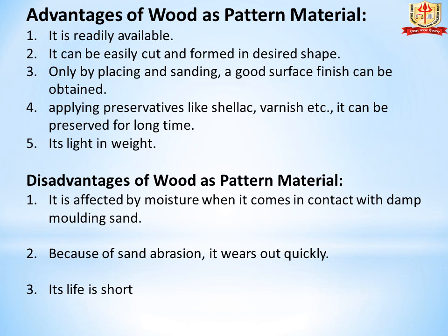Now see the advantages of wooden patterns. Advantages of wood as pattern material. First, it is readily available. Second, it can be easily cut and formed into a desired shape. Third, by planing and sanding a good surface finish can be obtained. Point number 4, by applying preservatives like shellac, varnish, etc., it can be preserved for a long time. Point number 5, it is light in weight.